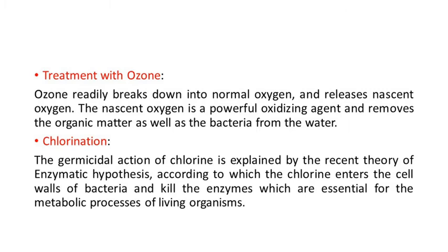Okay, if you apply 2 ml of chlorine, at the end of the tap there may be 0.2 to 0.5 ppm of chlorine available. So that is the dose of chlorine always available in the water. If chlorine is available in the water, it reduces the chances of contamination of water, reduces the chances of growth of bacteria, and reduces the metabolic activities. That is the advantage of the presence of chlorine in the water.